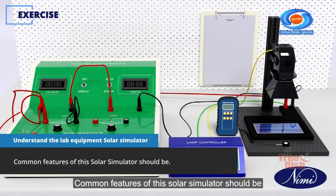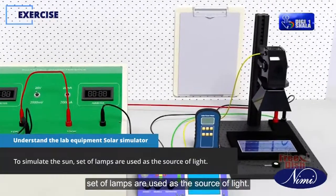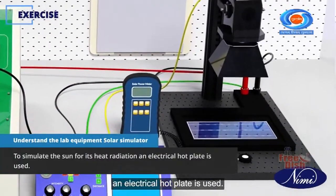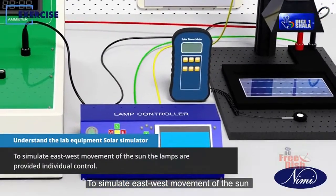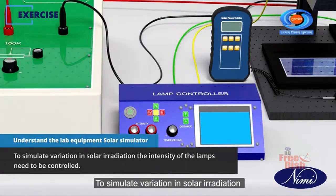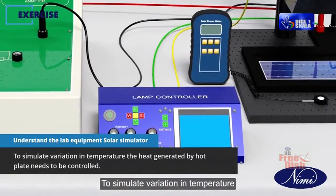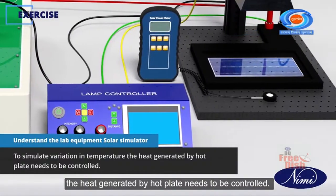Common features of this solar simulator should be: to simulate the sun, set of lamps are used as the source of light. To simulate the sun for its heat radiation, an electrical hot plate is used. To simulate east-west movement of the sun, the lamps are provided individual control. To simulate variation in solar irradiation, the intensity of the lamps need to be controlled. To simulate variation in temperature, the heat generated by hot plate needs to be controlled.